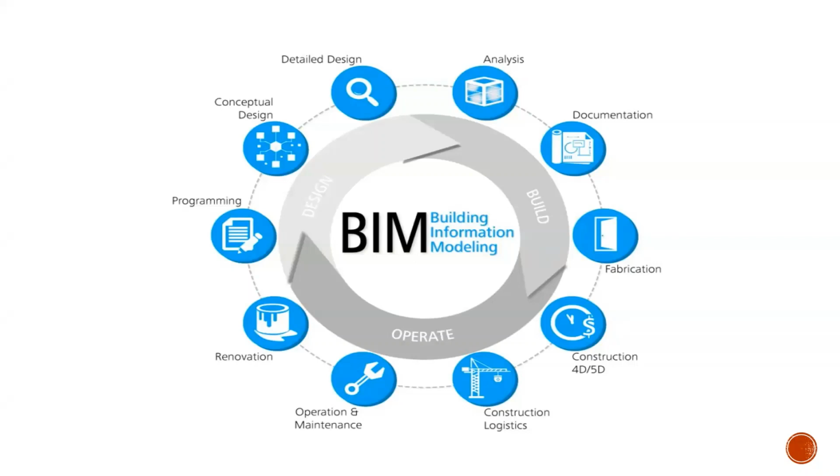Summer sun has to be blocked. Like that, I have to provide the shading shadow analysis. If I am providing a building in an urban area where I have a pack of buildings, I have to go for a shadow analysis. I have to check whether the other buildings are casting shadows on my building, and in that area maybe I can avoid that shading.